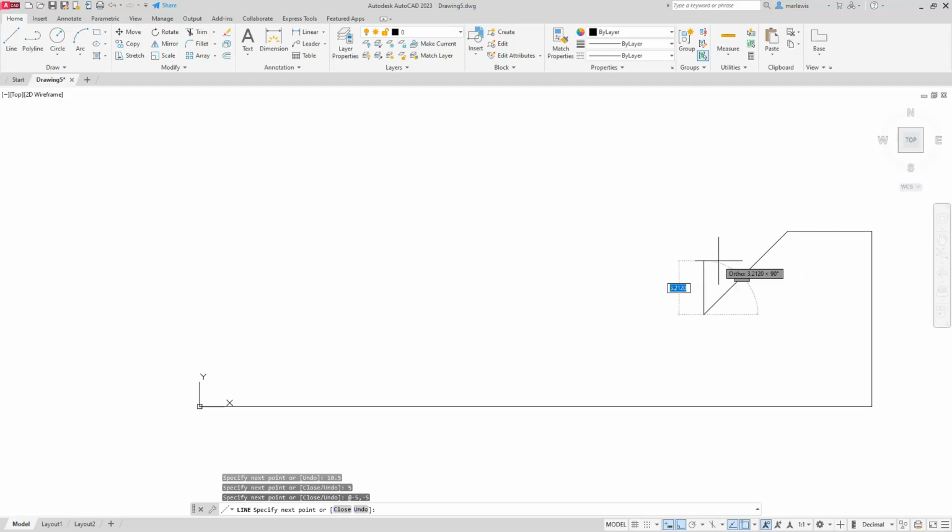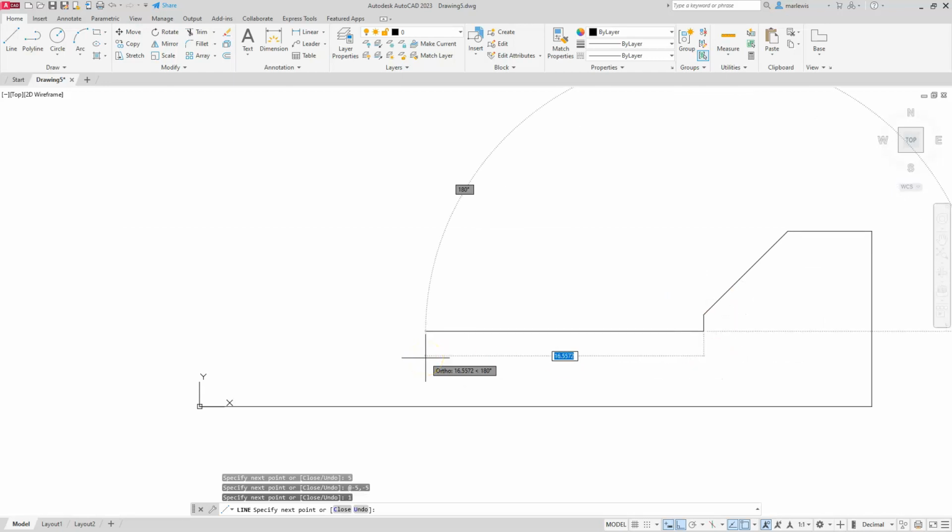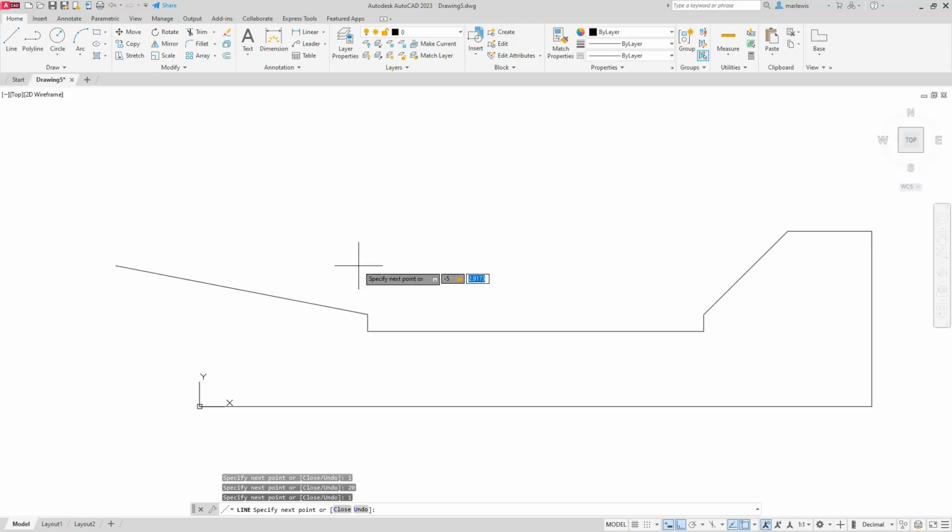Enter. Then I'm going to come down a distance of 1. Enter. Let's go back to the left here, 20. Let's go up 1. And then we have to put in those rectangular components again. We're still headed left on the X-axis, so therefore that's a -5, comma, and we're going up in the Y direction, so this is just going to be 5. Enter. Let's go back to the left, a distance of 5.